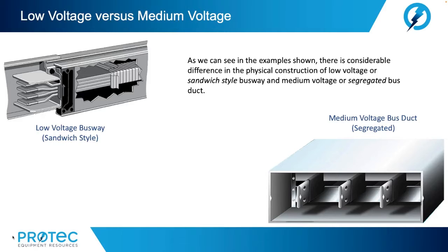Now let's take a look at low voltage versus medium voltage structures. As we can see in this example shown, there is considerable difference in the physical construction of low voltage, or sometimes called sandwich style busway, and medium voltage, or sometimes referred to as segregated bus duct.